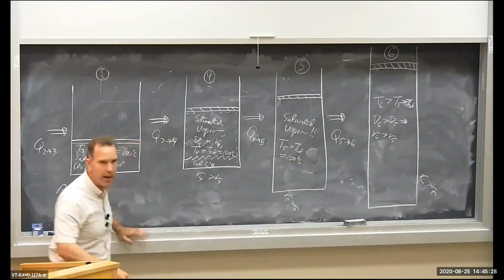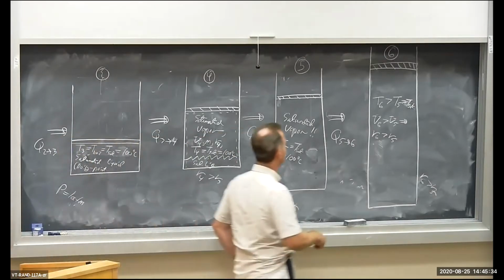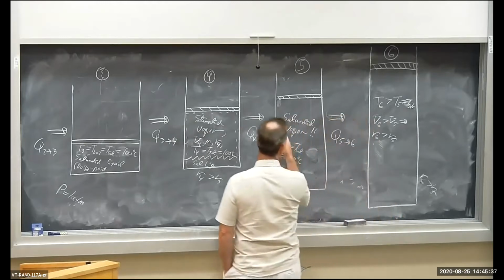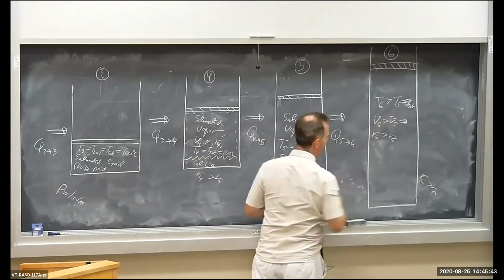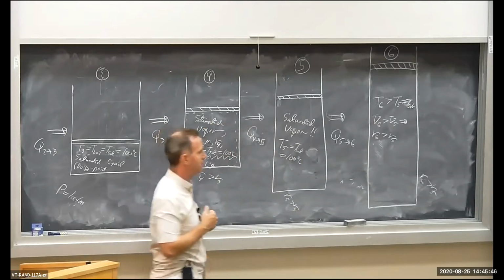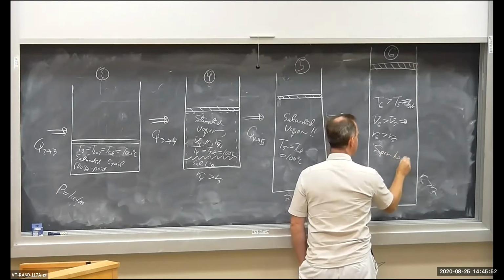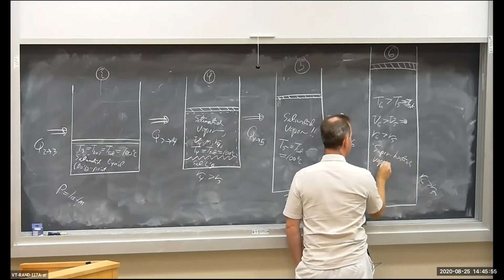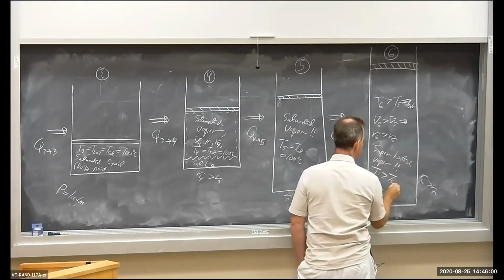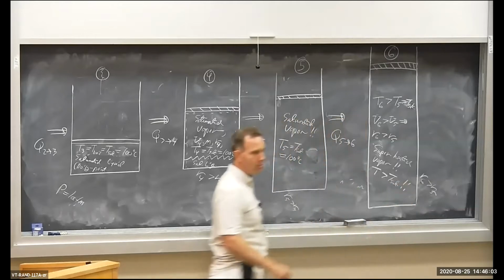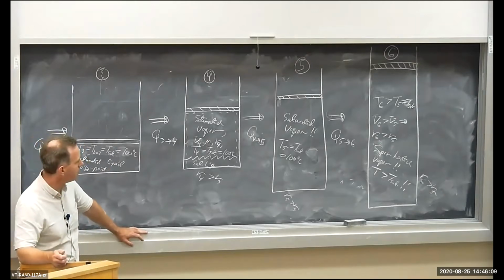Specific volume is volume divided by mass. The mass isn't going anywhere. There's still the same amount of H2O in there. But now, instead of having a saturated vapor, it's now hotter. It's hotter than the saturation temperature, so it's superheated vapor. Why? Because temperature is greater than Tsat. Temperature is greater than Tsat, or the boiling temperature, so it is superheated.